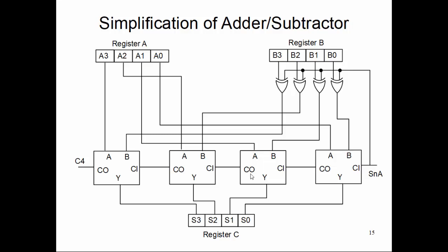So this will take care of feeding either the inverted or the same non-inverted value into the full adder, depending on which mode you are choosing, whether you are choosing addition by setting SNA to 0, or subtraction by setting SNA to 1.